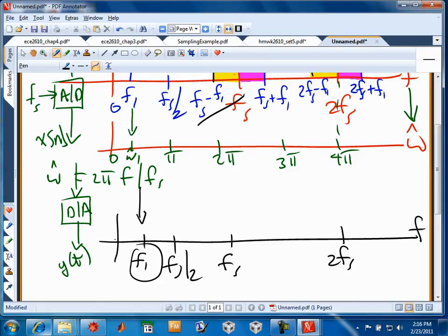That's the theme of the last homework problem. In the end, it just says follow the rules. Bring an input into the A to D converter that fits within the band 0 to Fs over 2, and it will come back out the D to A converter at the same exact frequency it went in at. So that's playing by the rules. If you bring a sinusoid in that's greater than Fs over 2, then it's going to alias down to something in the principal alias band, and it's going to come out at that alias frequency, which is not playing by the rules. You're basically accepting the consequences.